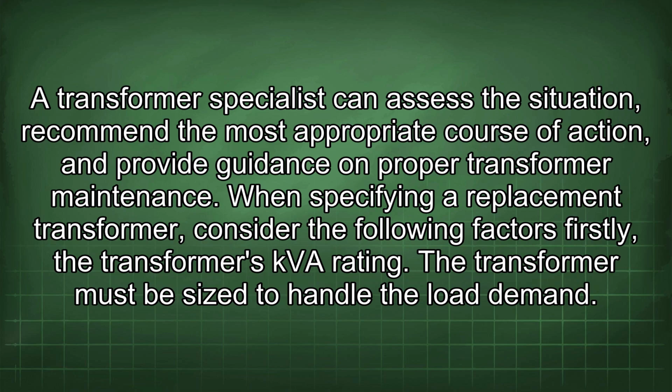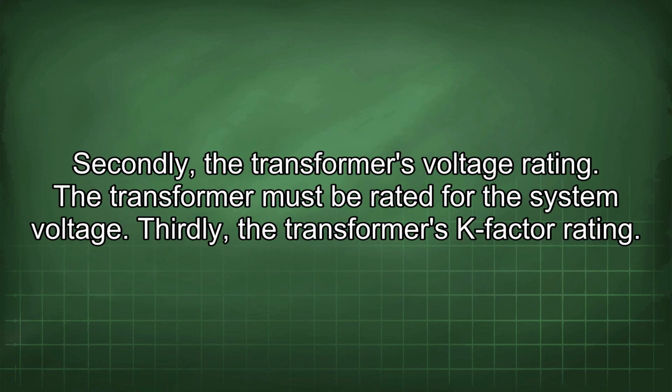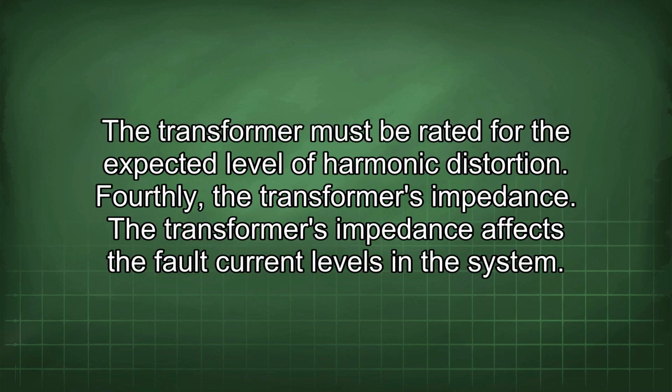Firstly, the transformer's kVA rating. The transformer must be sized to handle the load demand. Secondly, the transformer's voltage rating. The transformer must be rated for the system voltage. Thirdly, the transformer's K-factor rating. The transformer must be rated for the expected level of harmonic distortion.